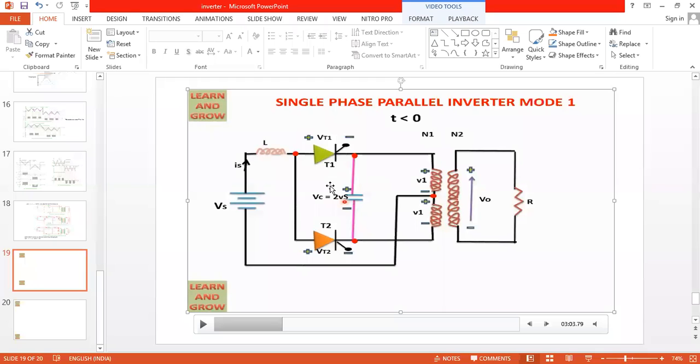10 volts. So that's why the capacitor charges to twice the source voltage, because of these two upper and lower windings. This is the advantage of the center tap. So why are we not using the inductor here? I want to charge the capacitor to the maximum value, double the rated value. It is possible only with this center tap transformer.